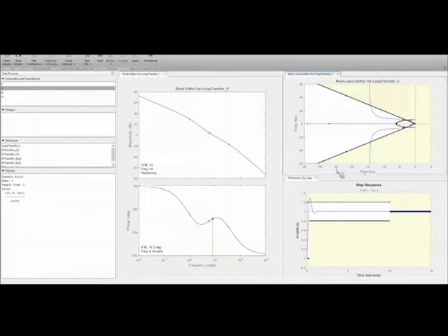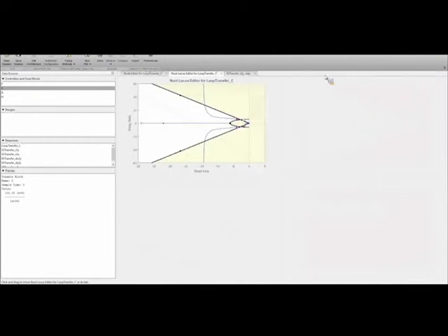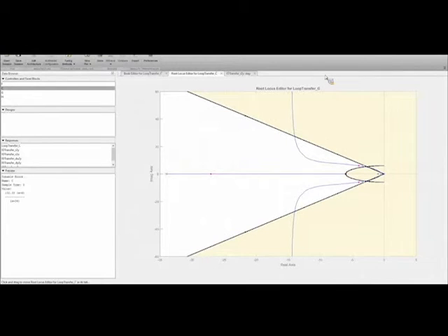Okay, so we can see a few things here. We'll talk about the step response and why that's just a little bit off in a second. Let's talk about the locus first. All right, so this is essentially what we drew. Let's see, how do I get this? The location here should be almost exactly at -4, -6. Now we did some rounding, like 41 is not the exact number, but this location should be almost exactly on -4, -6.